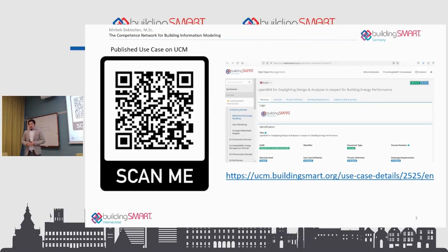Well, unfortunately, there is no bSDD API for Revit yet, and currently what I used was a SketchUp bSDD API. It worked well, so I didn't have to. It's really tricky and time consuming to create the custom properties in any BIM authoring tool. You have to create a property, you have to check how it looks.